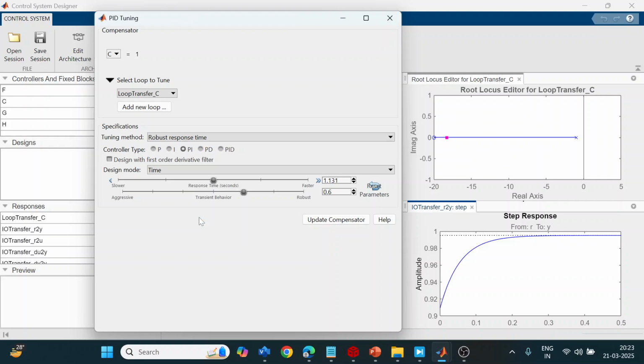Now it depends on what the requirement is. Suppose you want to design a PI controller, you require a bandwidth which is very low or high, depending upon the system. For voltage control, it requires less bandwidth, but if you go for high frequency current control, you require a faster bandwidth. So in that case you need to specify the bandwidth. Okay, so you can go for PI.